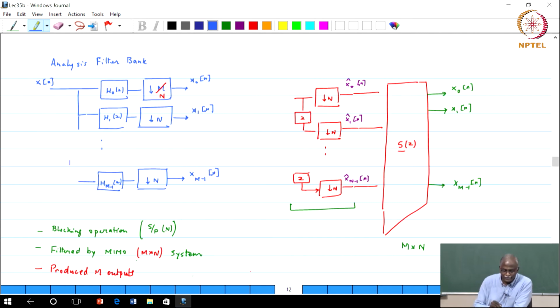So, basically this is the structure of the polyphase analysis filters. Since you have upsampled by N, which means the introduction of redundancy, you must downsample by N in order to remove the redundancy, because at the end of the day you want to have the original signal back. So, basically we are doing the downsampling by N, following the same procedure, doing polyphase decomposition, and then the noble identity, we get the following structure. Okay. So, I am assuming this part of it you are able to review and are comfortable with.